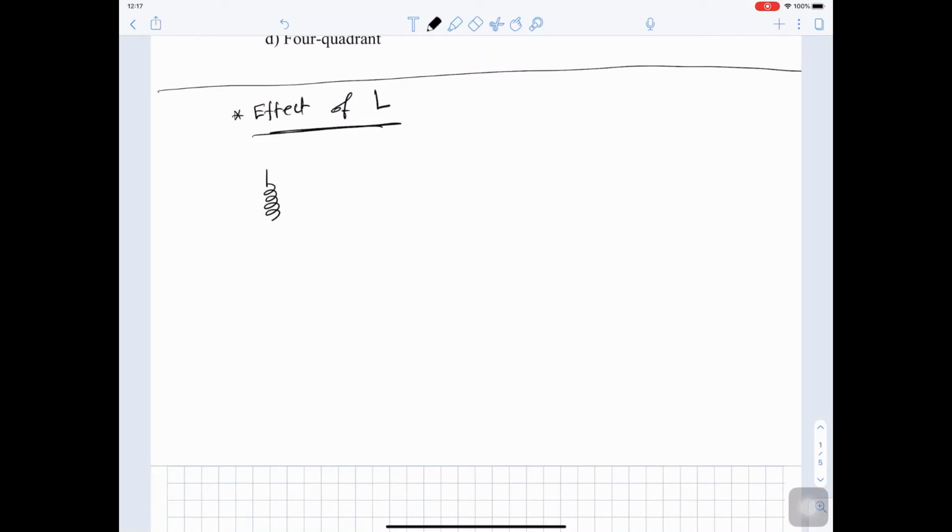If we have an inductance with a value L, and if you remember, the inductance is a coil around a core which can store flux phi inside the core. The equation relating its current to the voltage across it is V equals L di by dt. This equation follows the load notation, so I is entering the positive terminal.